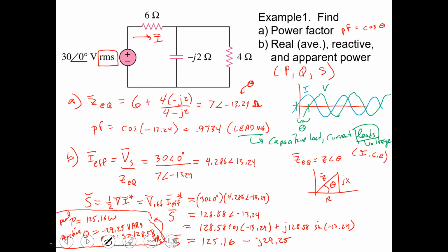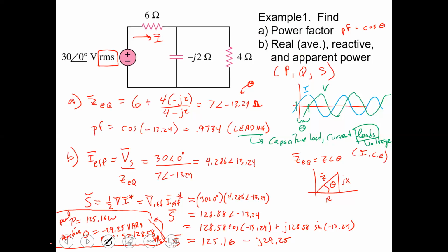So it's just dividing by 2 if you get it in magnitudes. If you get it in magnitudes, it's 1/2 of the product of the magnitudes of the voltage and current. Because each one of them is divided by the square root of 2, so that squares that and gives you a 2.